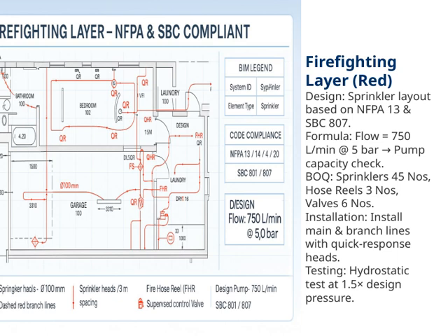effectiveness. When we consider the formula for flow, we're aiming for a capacity of 750 liters per minute at 5 bar pressure. This is crucial because it helps us verify whether the pumps we select can deliver the necessary water flow and pressure in case of a fire.